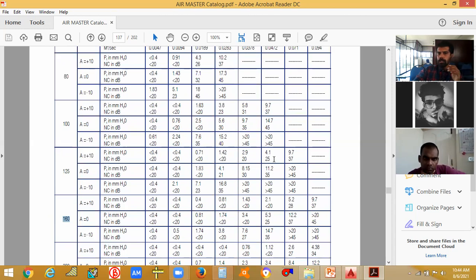So this is the way that you choose the air terminals. Here we are choosing the disc valve. Without a catalog also, you can go to the software known as beta software and you can get the size. I don't know whether you will be getting the disc valve. Rest everything you will be getting from the beta software. For the disc valve, you go like this and you choose it. NC should be maximum 35.